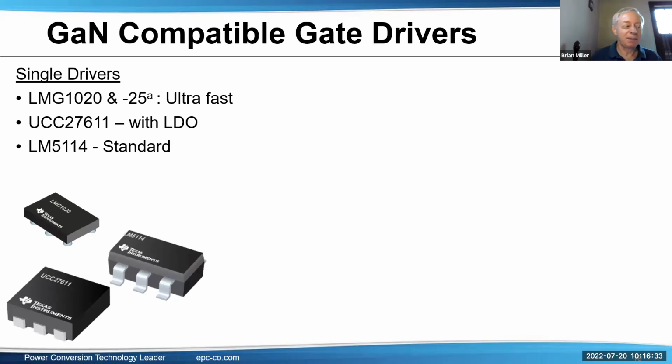There's been a very nice collection of gate drivers that has been growing, especially in the last few years. There's really quite a good assortment. Single drivers have just a single input and single output to drive a single FET. There's more than shown here, but 3 key ones are from TI: LMG1020 and the 25. These are very fast and also very small. They're great for small sizes or when you need a very fast driver. Beyond power supplies, they're used in pulsing lasers and so forth. So they're very, very good drivers. There's others with or without LDOs integrated into them for 5-volt gate drive.